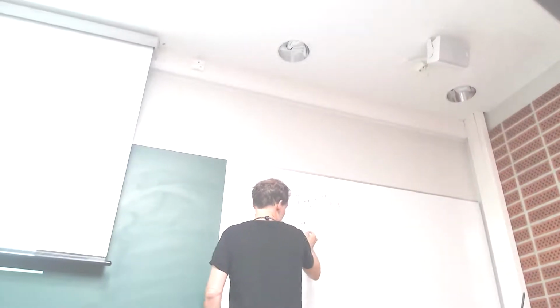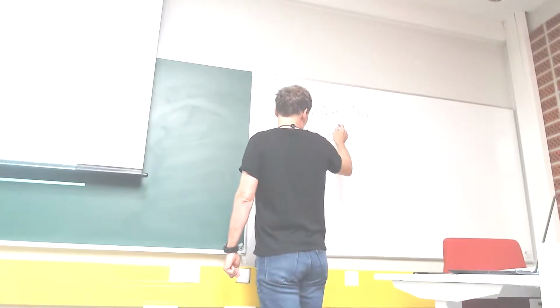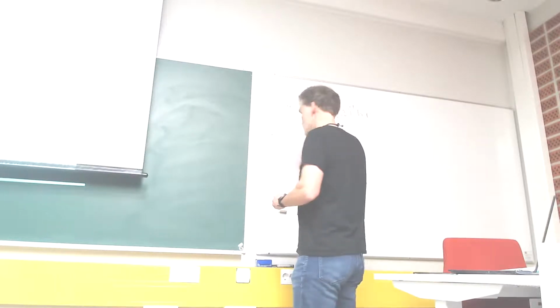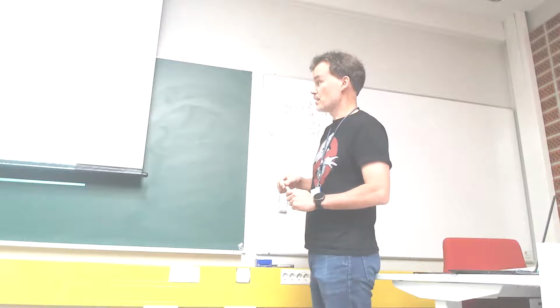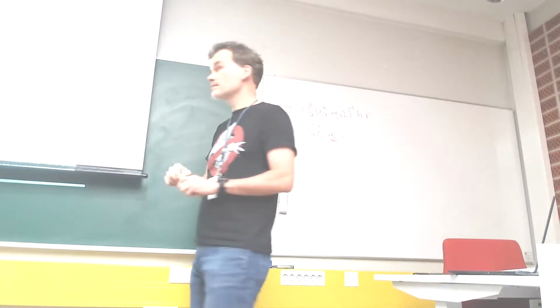So basically, it's a normalization by SNR. It takes into account the noise versus the power when normalizing the received signal. When the SNR is large, alpha becomes 1, either because this term becomes small or this term becomes large.